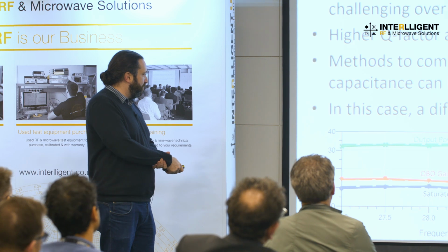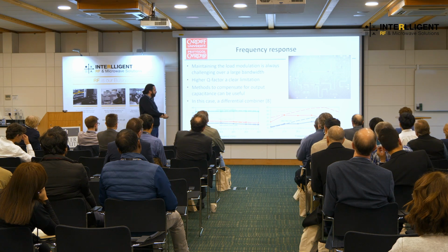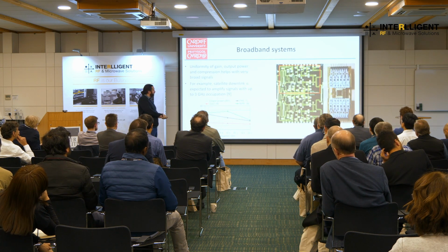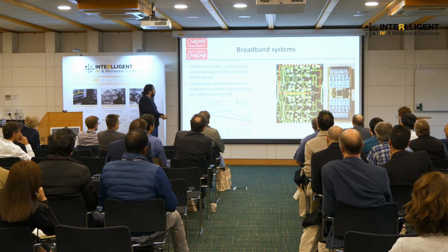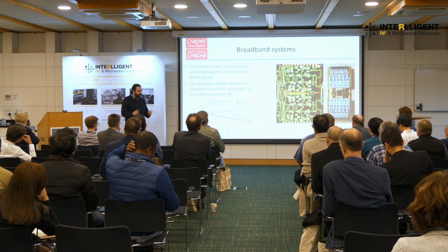Performance was quite good in terms of back-off efficiency, getting near the 30s, which is always a good result for 20 gigahertz. And then, very recent, so I didn't do much on the design in this one, but I did all the load pull characterization in collaboration with Politecnico di Torino. This is an ESA project. Published this recently. We tested it up to 3 gigahertz of bandwidth, so 17 to 20 gigahertz, more or less. So we have some good results of MPR up to there. These are results with 100 megahertz of channel bandwidth.